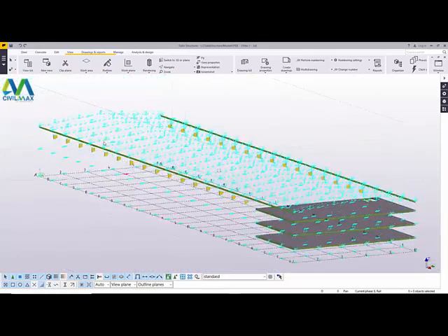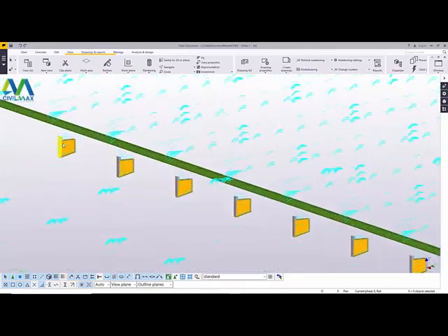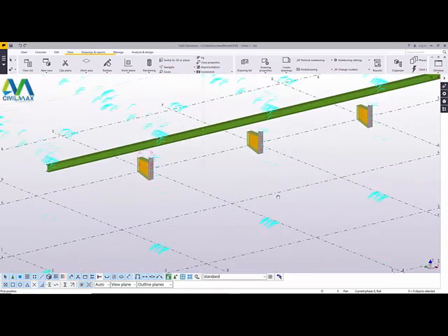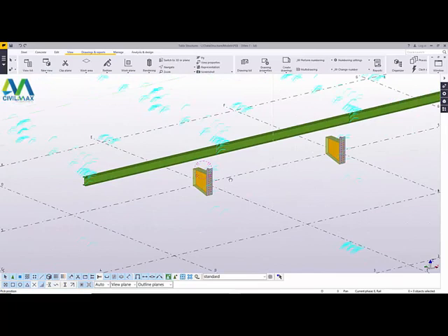Now where do we start? We want to start from this end here, and I'll come to navigate and turn that. Remember to rotate your model. There are two options. You can come to navigate and click on this drop down arrow and pick the first option. You can see a symbol of a mouse there, and another option, you come to your keyboard, press Ctrl Shift and hold your middle button on the mouse. The two options are available for you. Whichever works best for you, that is the tool that is ideal for you, that will make your work a bit faster. And for me, I use both.